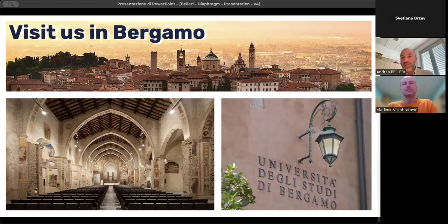Yes, no, but it's possible to strengthen existing systems of this kind. You can act from above with an additional topping, but then you need to remove the finishing. You can act from below, from the intrados, so you can provide a bracing system, or you can act from the outside, like Professor Marini in our group proposed, using an external diaphragm.